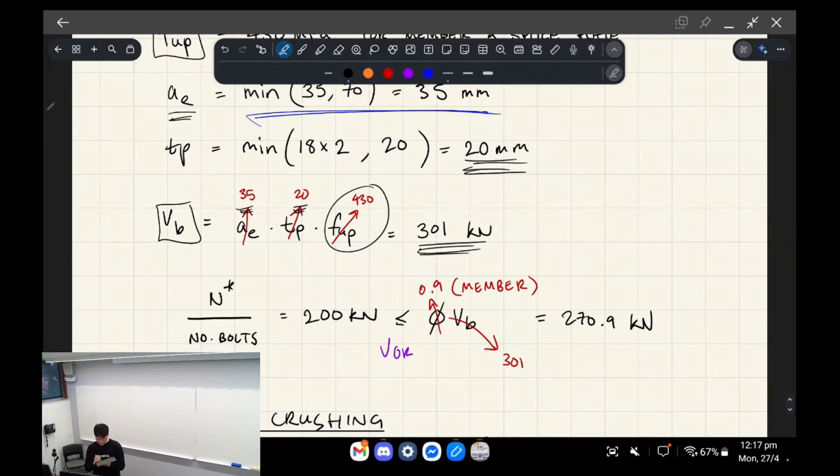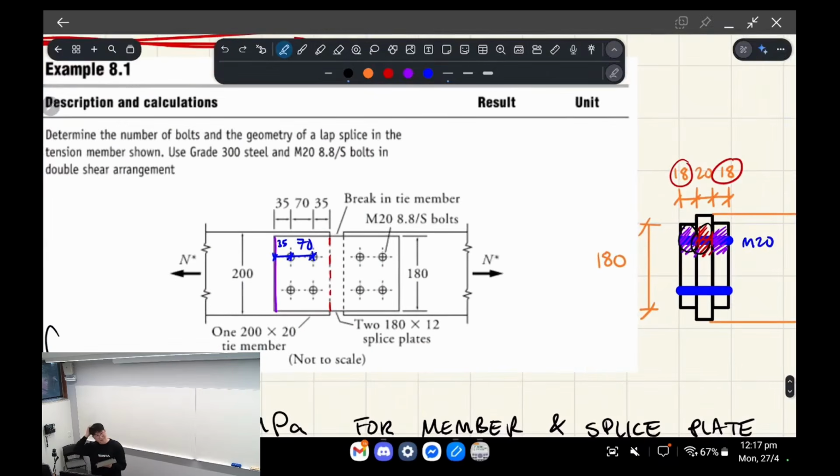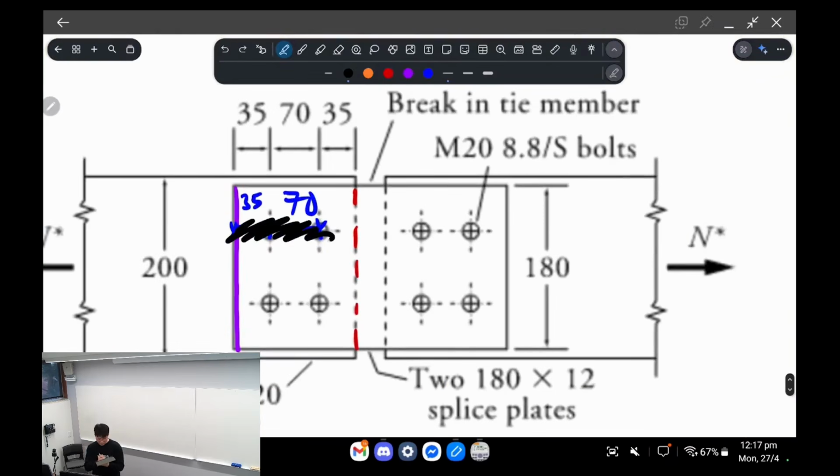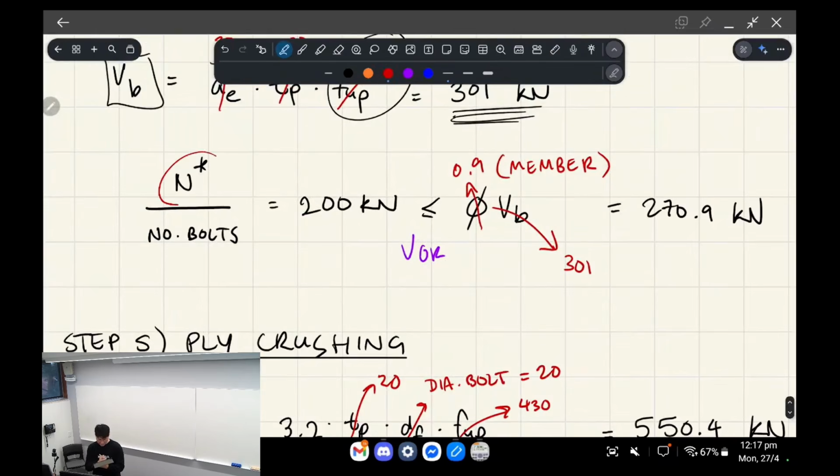And basically what you have to do is, you aren't checking this. So here's the weird part, right? Because you're using the member itself's material properties, but you're checking how much force is being applied through one bolt, okay? So because all 4 of these bolts are kind of moving in tandem, the idea is you essentially divide whatever load you had by the number of bolts.